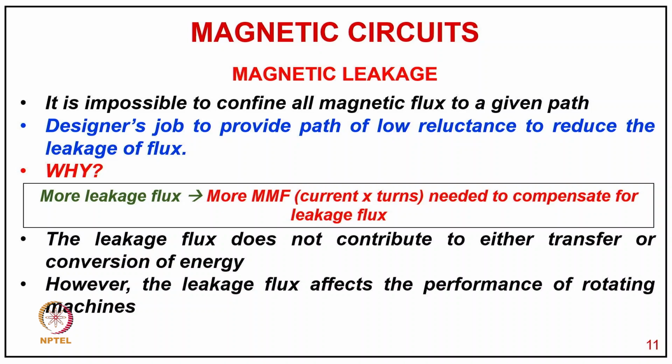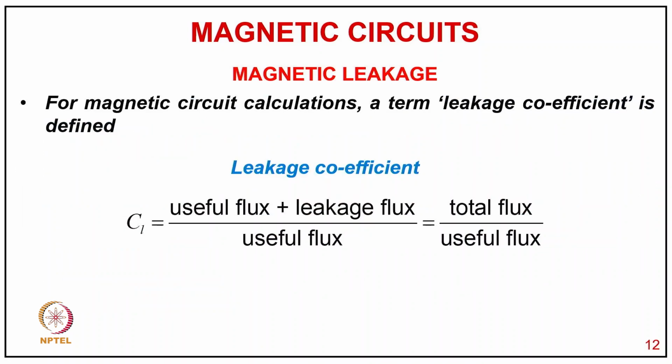And why is leakage flux a concern? More MMF and current are needed to compensate for the leakage flux, which, however, does not contribute to energy conversion, the requirement of these machines. So leakage flux does not contribute to the conversion of energy, however, it affects the performance of rotating machines.